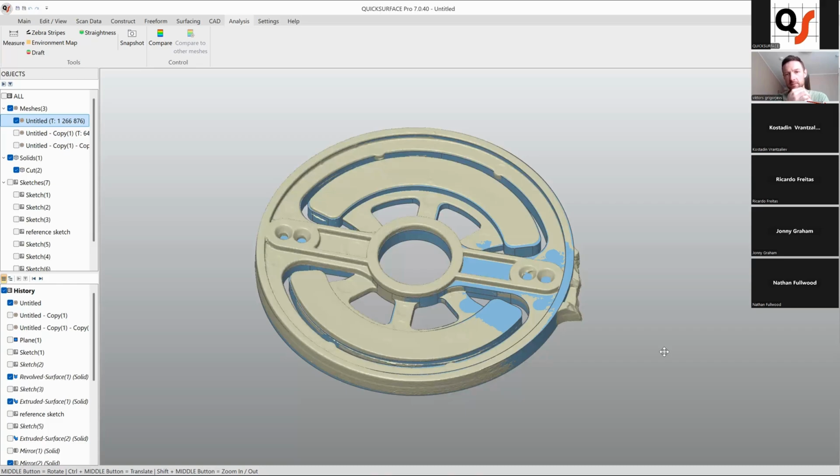There was another question. What happened with the tolerance comparison along the mirror plane? Well, what you just saw was a pure mirroring of the mesh using a specified plane. What you probably got confused with is what's called the symmetry plane, which is a different story. The symmetry plane uses perfectly scanned data to find where the plane of symmetry is, and then you have this tolerance that you can see.